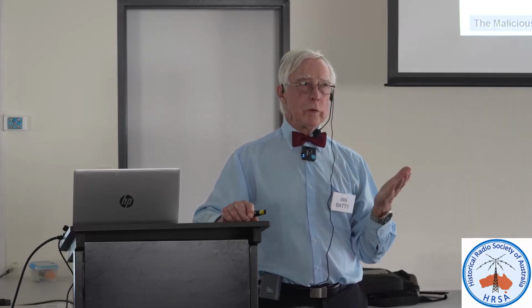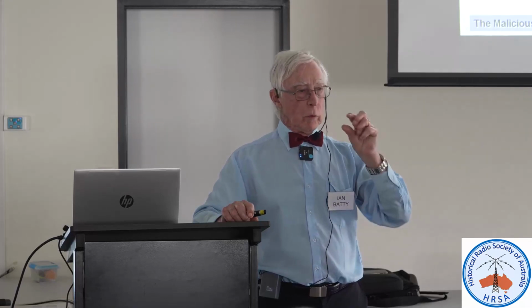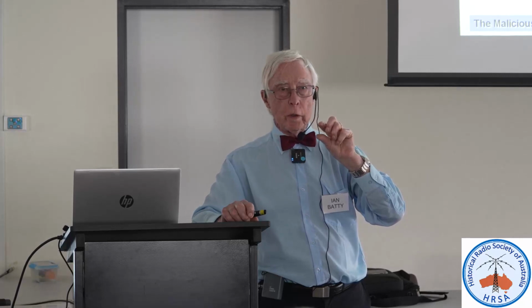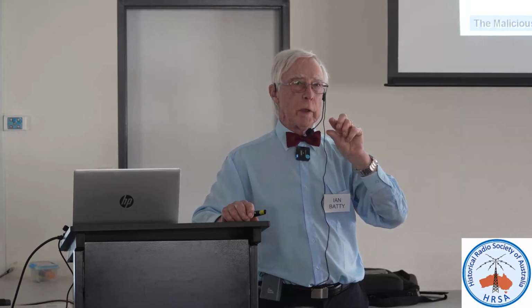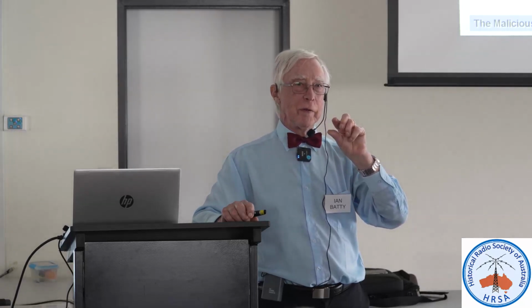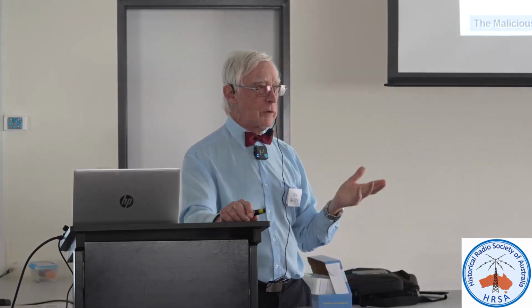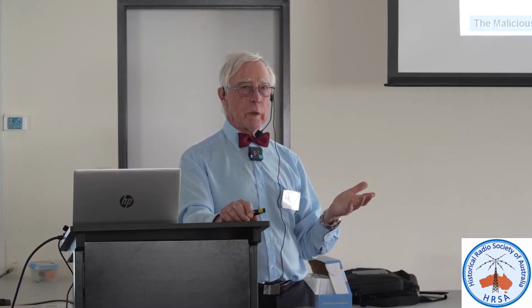Ceramic capacitors are usually okay, but those little red tip ceramic capacitors they use in transistor radios, I have found some of them to be leaky. And I got a shake of the head there. Yeah. I agree with you, it's right. Okay, so capacitors are the most suspect.